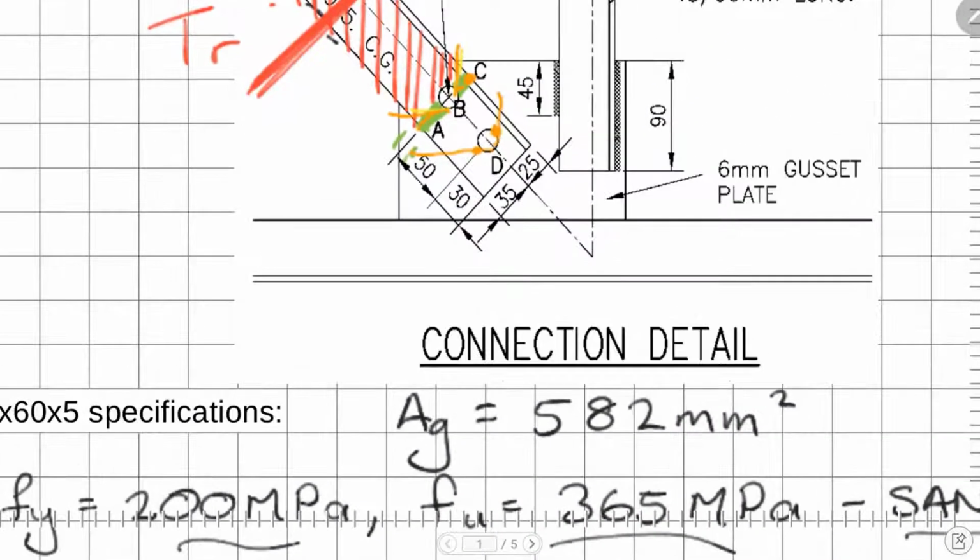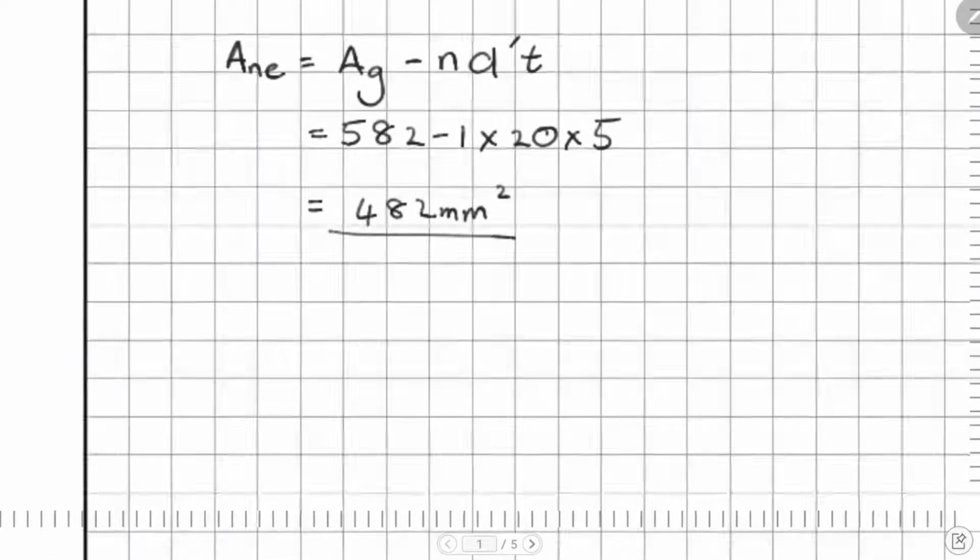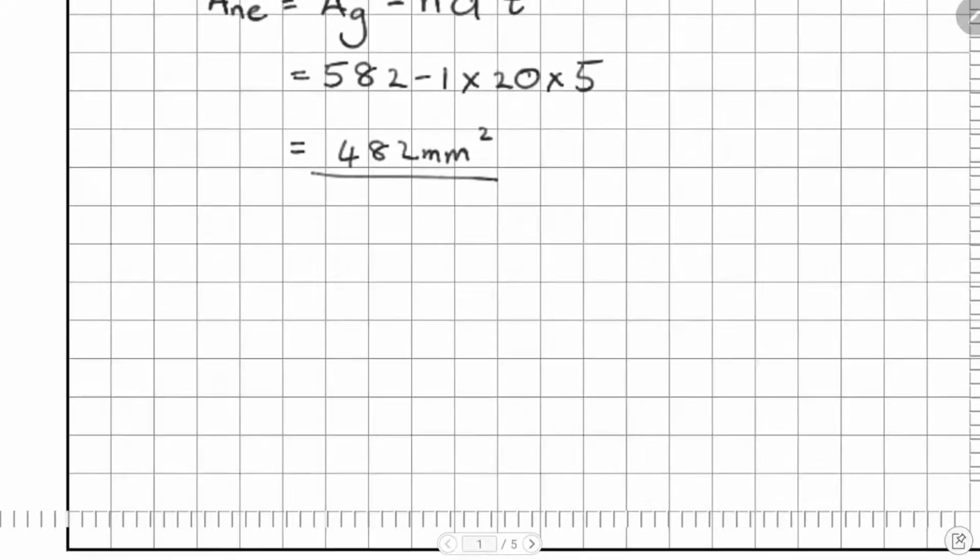And the more bolts we have down the length, the better. So we have 2 bolts right now. If we had, for instance, 3 bolts or 4 bolts or 5 bolts or 6 bolts, the more bolts down the length, the better, because there's more length to distribute load out into the section, and the more efficient, because it'll fail at the front line, the more efficient it'll be where it fails. So this is a section, for angles, with less than 4 transverse lines of bolts.